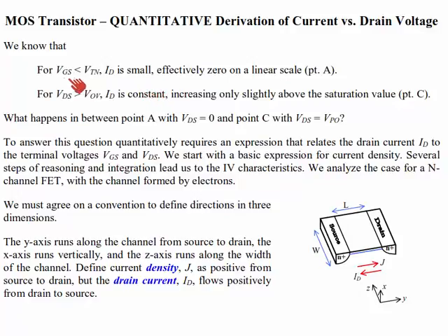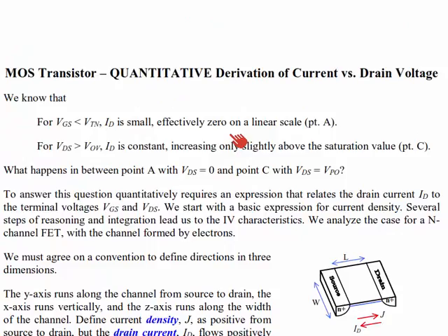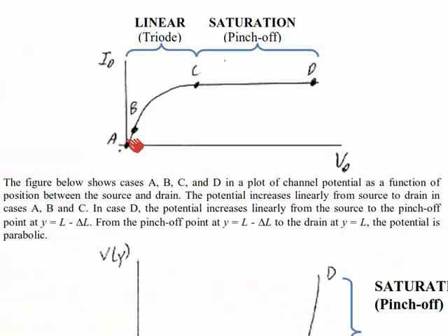When the drain to source voltage starts increasing, we get first a linear increase in the drain current, and then as the channel pinches off, the resistance increases, and the current voltage characteristic bends over till it becomes almost horizontal. For most of our hand analysis, we'll assume that the saturation region remains horizontal and just correct for it when it doesn't.